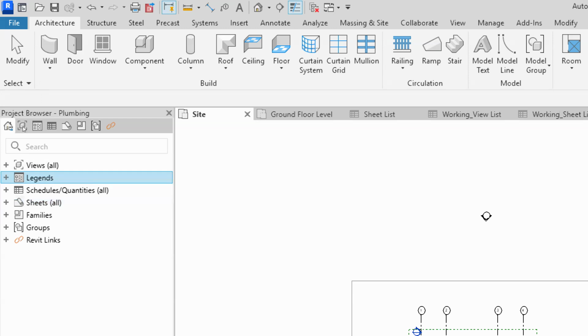The sheet doesn't necessarily have to be composed of only views or only legends. If you are doing a door and window schedule sheet, for instance, they need to be able to show a layout showing the doors and windows on the drawing before you add the door and window schedules, before you add the door and window legend, so that the person can see where the windows are on plan, how they are depicted, the legends, and then how they are scheduled also. That will compose a sheet.